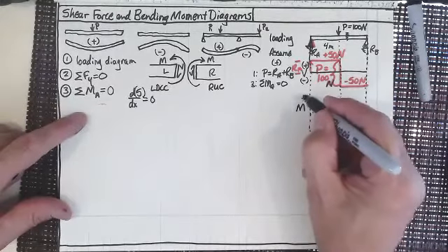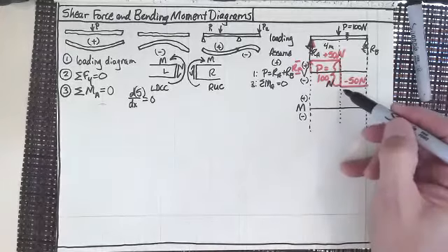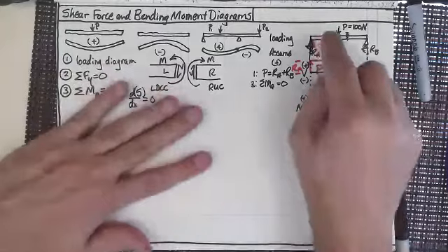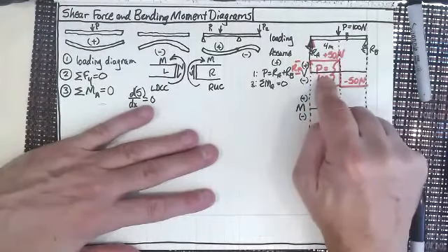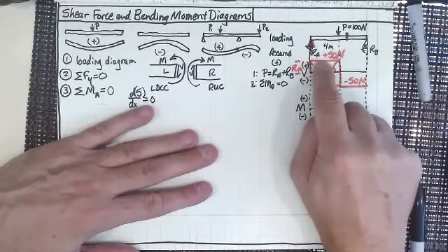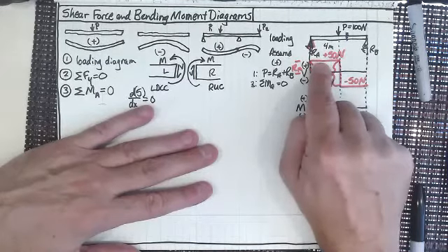And again, bending plus, minus. You're probably thinking, well, it's all going to be in the positive side then, right? Well, we know that this is 0, so we know that the slope of the line in the shear force diagram has got to be 0, right? So that's 0, and if it's a constant, the derivative of a constant is 0.